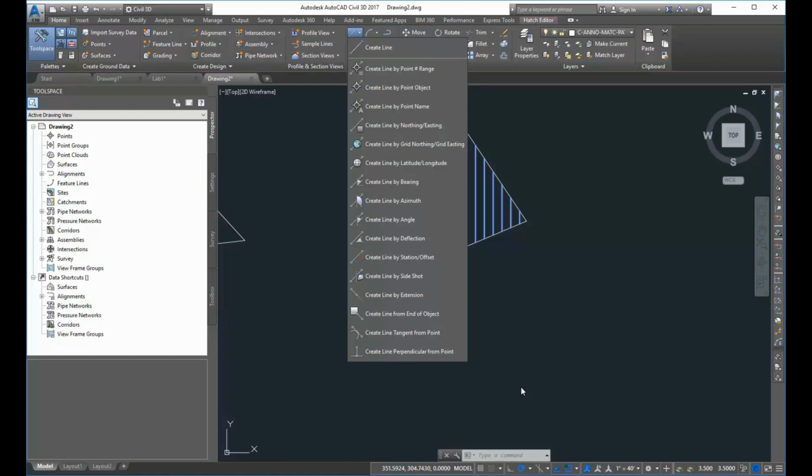You're defining a parcel that goes all the way around, and you will close at the beginning when you draw your last bearing. If you were to zoom in really close, you'll find that, because of the number of decimal places, the bearing distance won't close exactly, but as long as you're zoomed out a little bit, it'll look like you're closed. That's how you'll know that you've done the lines by bearings correctly.